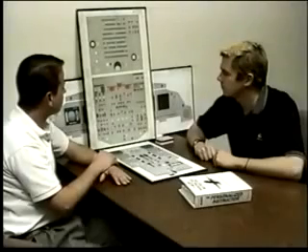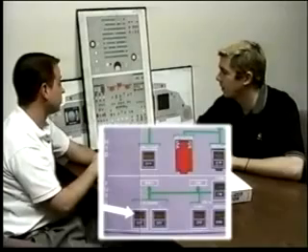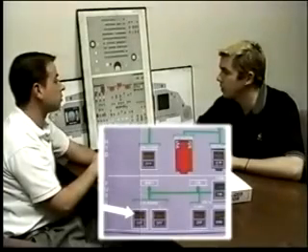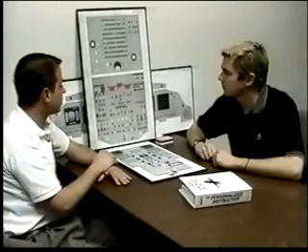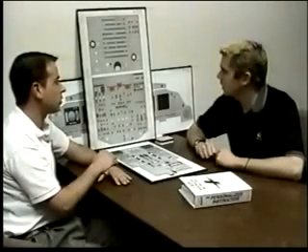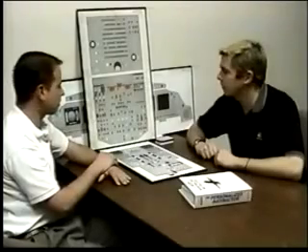Fault lights. Describe to me a fault light in a wing tank pump. A fault light in a wing tank just means that there's low pump pressure. Fuel numbers. Are there some numbers associated, some limitations that you can come up with for the fuel system? Yeah, we've got a new one at United, the fuel imbalance.